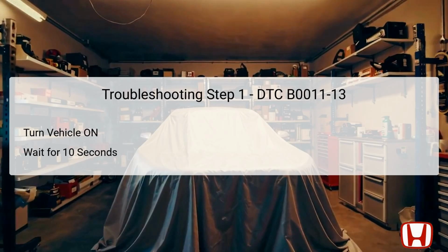Waiting allows the SRS unit to initialize and could reveal if the DTC persists or resolves itself under normal operational conditions. It establishes a baseline state from which further inspections can be conducted. This step is crucial as it may indicate whether the error is transient or a fixed issue that requires more in-depth evaluation.